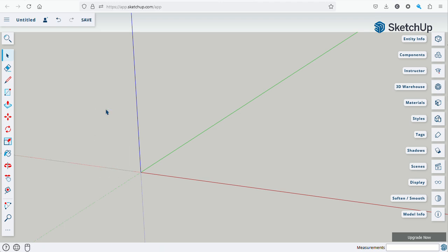Just click the delete button on my keyboard, and now I'm going to draw a square 60 millimeters by 60 millimeters. Now, because of the scale, have a look at the bottom right hand corner of the screen, and you can see the dimensions of the rectangle I'm drawing in millimeters, and it's like 2190 millimeters. Now that is crazily too big.